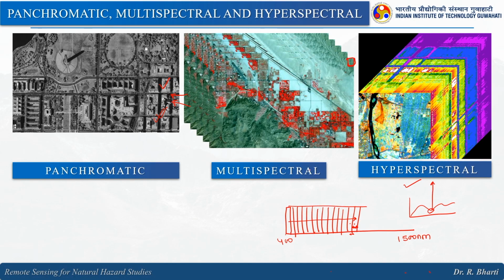If you want to identify just the material, not the composition, multispectral is better. If you want detailed information about how many trees are there, how many houses are there, how many cars are located in one street, then in such a situation panchromatic images will be better.